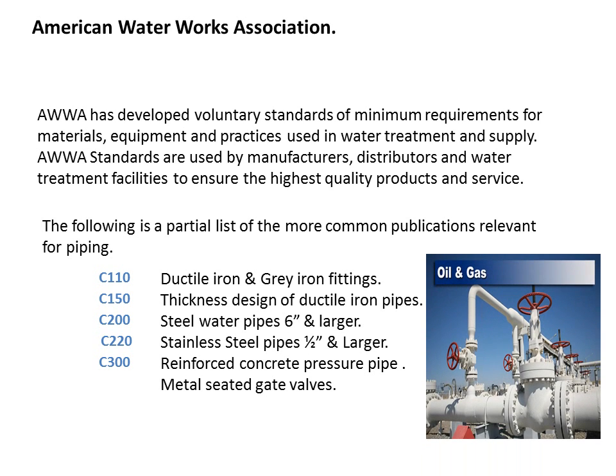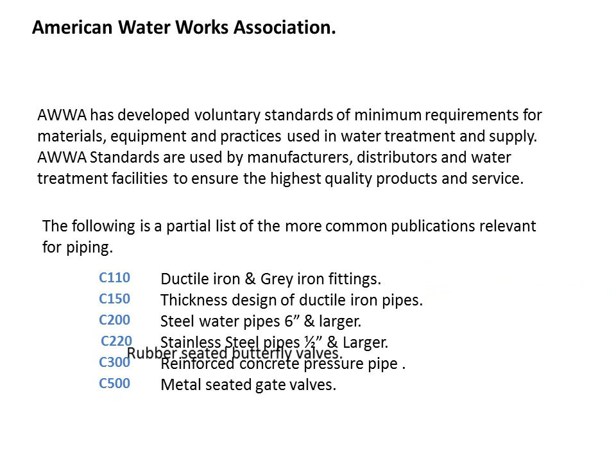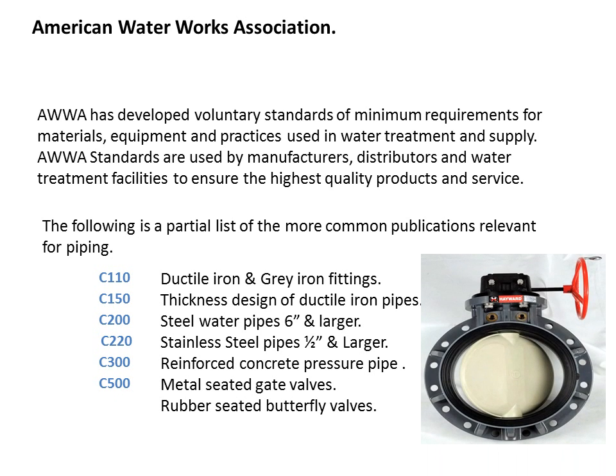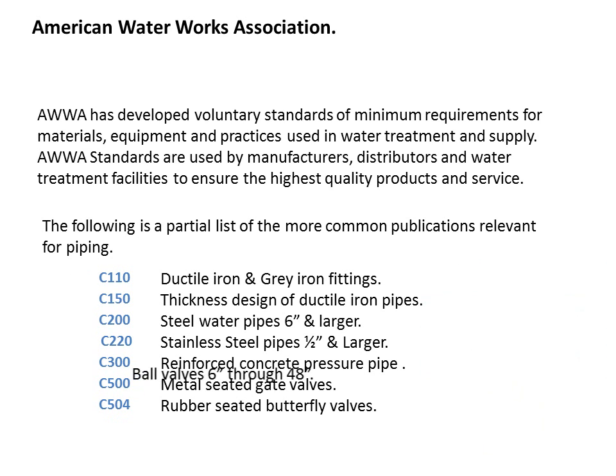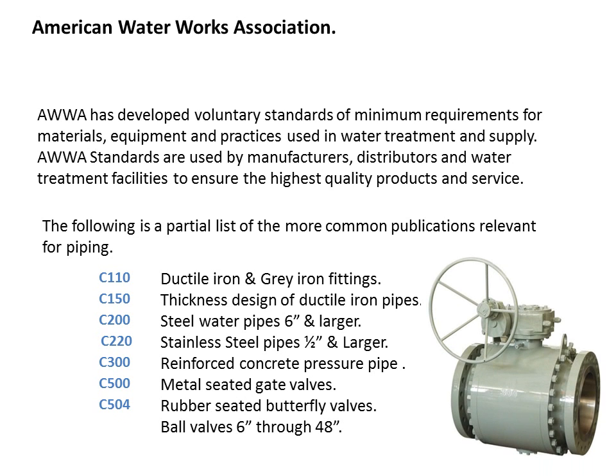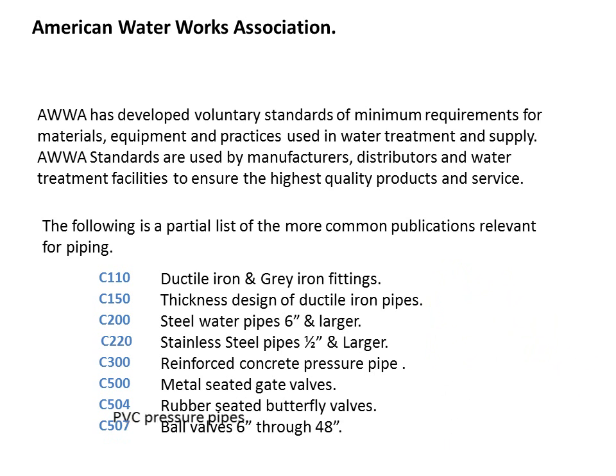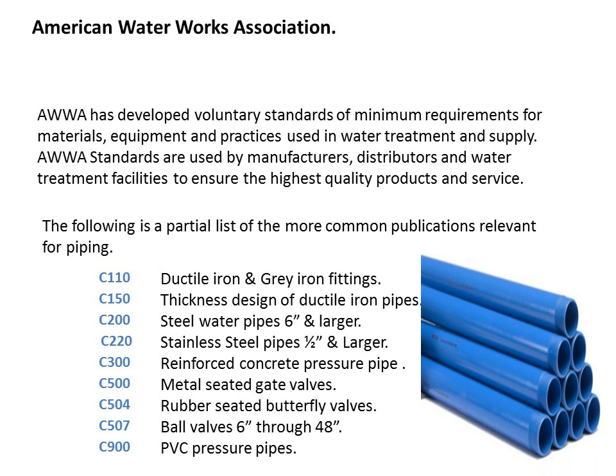For metal seated gate valves, we have standard C500. For rubber seated butterfly valve, we have C504. For ball valve 6 inches through 48 inches, we have standard C507. And for PVC pressure pipes, we have standard C900. So various standards are there for the pipe and valves that have been illustrated over here.